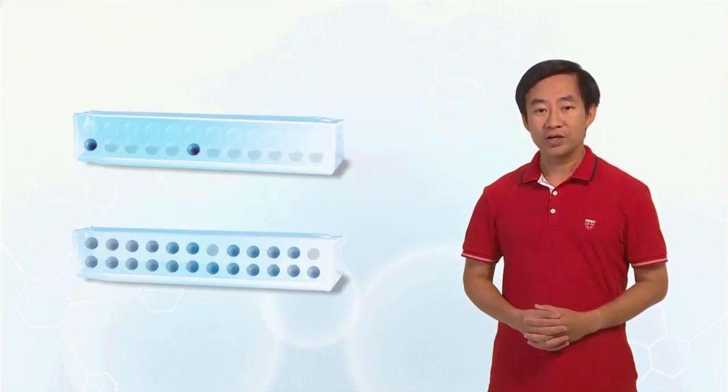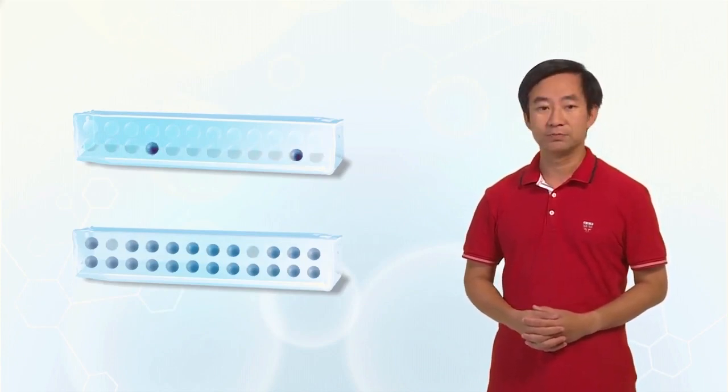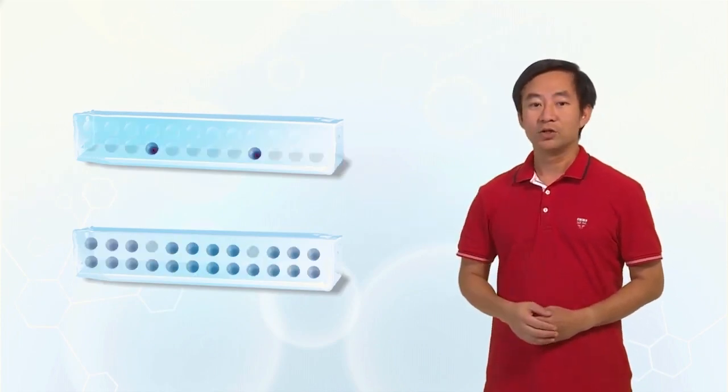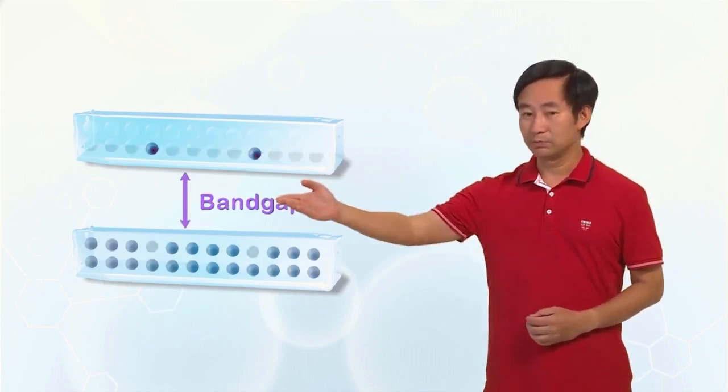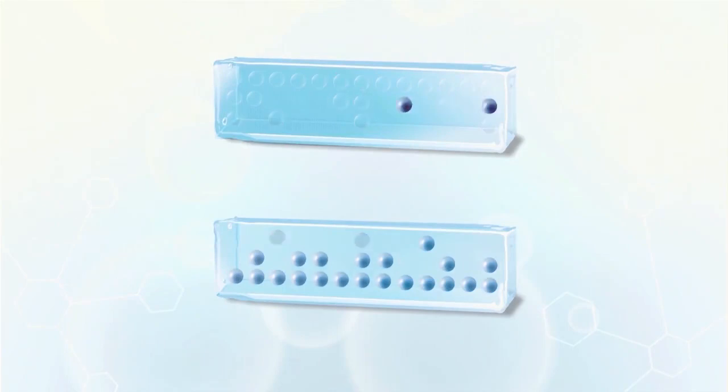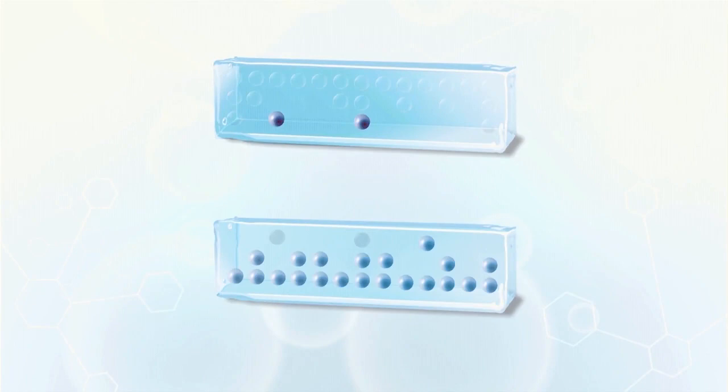The density of carriers in a solid semiconductor material depends on three factors: the density of state available in the energy band, the size of the band gap of the semiconductor, and the temperature of the operation environment. Let's start with the density of state. A state is just a space to hold one electron, and it becomes a hole without an electron.